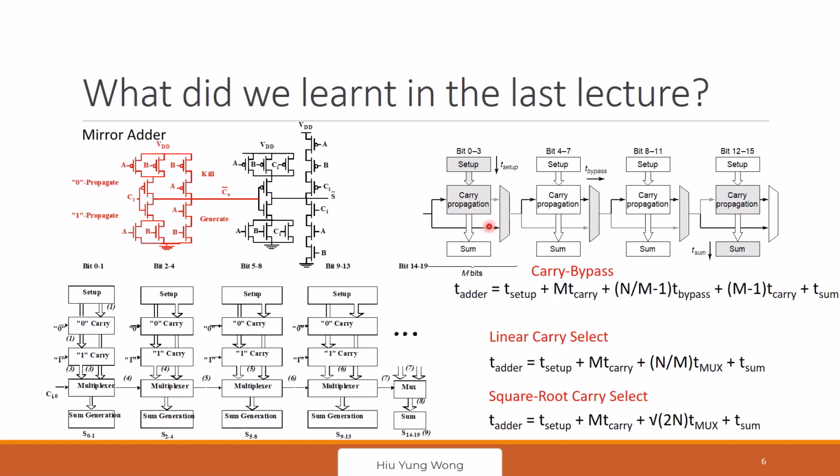Generation, yeah, propagation, yeah. All propagations should be 1 for it to select. Thank you very much. Right, we need P0, P1, P2, P3, right? Bypass, right? If they are all 1, then you will just take this one because this is a multiplexer, right? Otherwise, you will take the top, right?